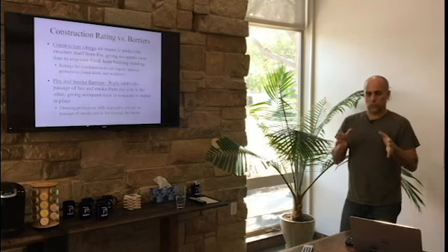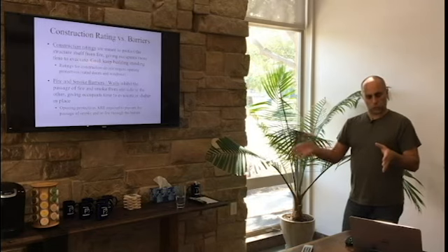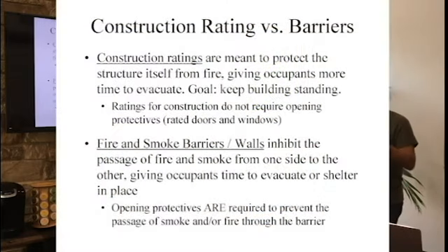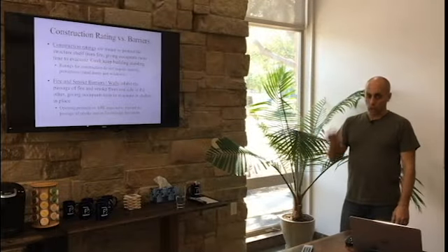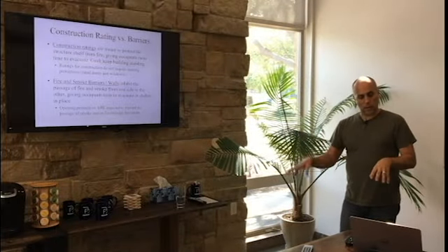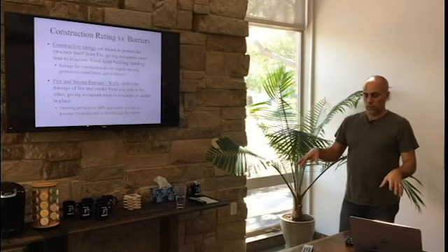Okay, construction ratings, which is per your construction type, which I'll get into in a second, is to keep the building standing. It has nothing to do with preventing the passage of smoke or fire going through, past, around, in any way, shape, or form. All we care about is the building staying up for the prescribed amount of time. 1 hour, 2 hour, that's pretty much it.